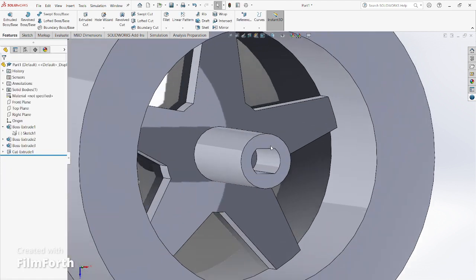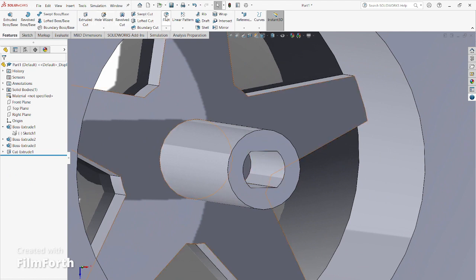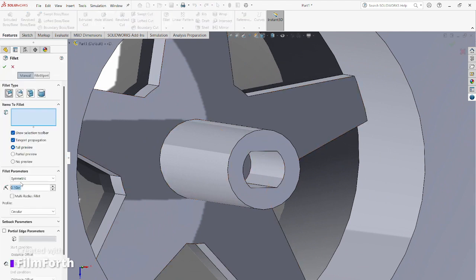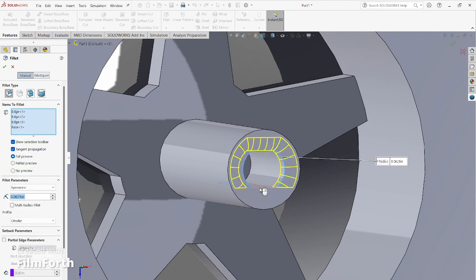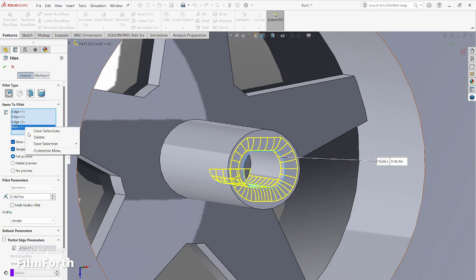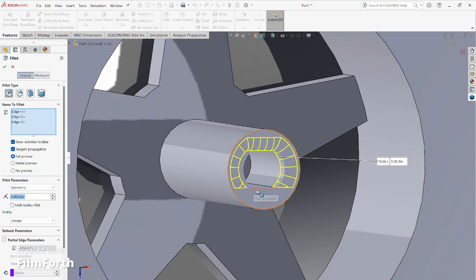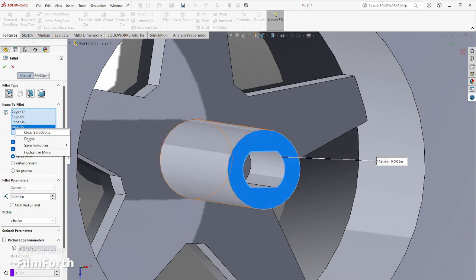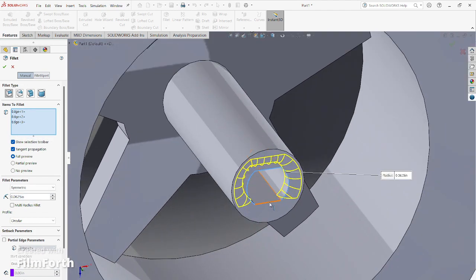That's it. And then finally, for the inside, I want to make the lip fillet. So I'm going to put it at 0.0625 as the smallest units. Whoops, 0.00. There we go. And I'm going to do it from the end, this lip right here on the edges, because we want the shaft of the motor to fit inside of it. Oh, come on, it's really difficult to get into it. I'm going to try a different angle. No, there we go.